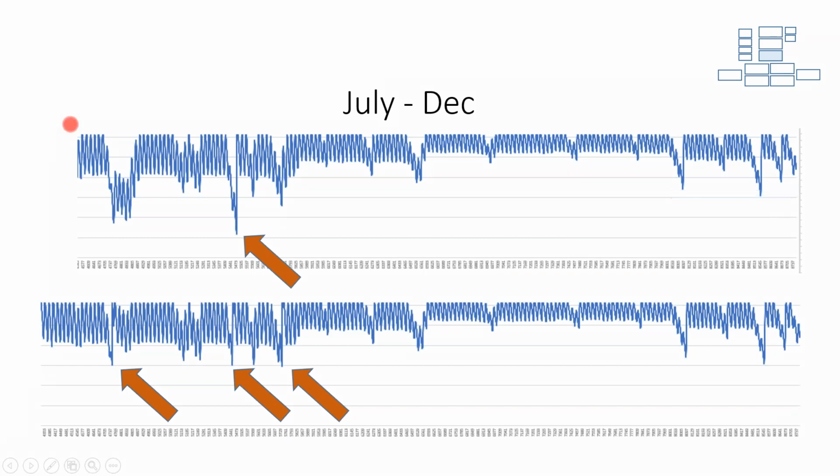Here we have July roll around, and this was kind of surprising. The deepest depth of discharge we get to is not in December or January, but it's actually in July. This might have been when a hurricane rolled off the Gulf Coast. Now we have a few days of thunderstorms with no sun, and because we have a huge air conditioning load, our battery starts getting dragged down, dragged down, and dragged down. And that's our 20% point, where the batteries are rated for no more than an 80% depth of discharge. That's how we sized the battery to be 122 kilowatt hours.